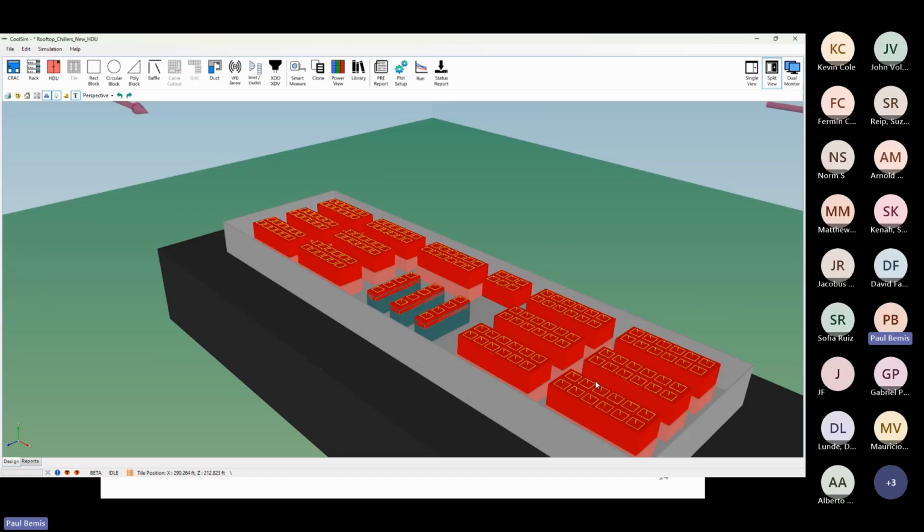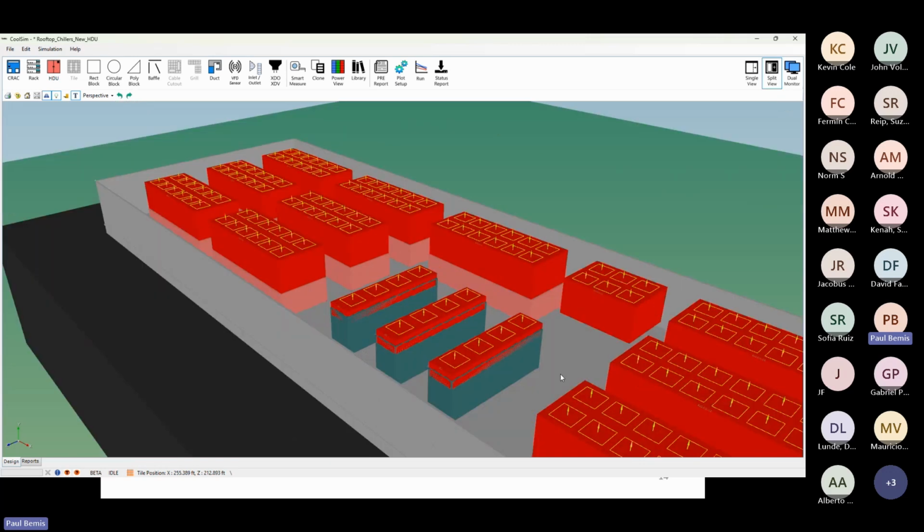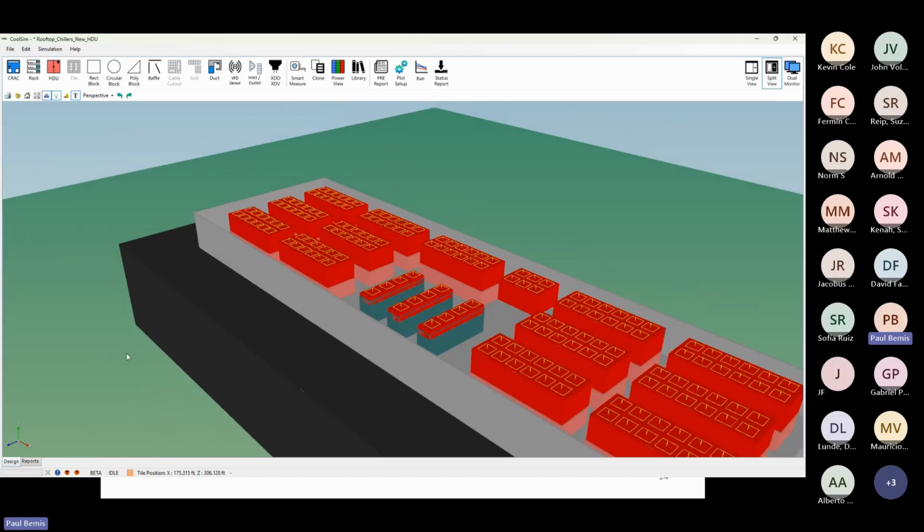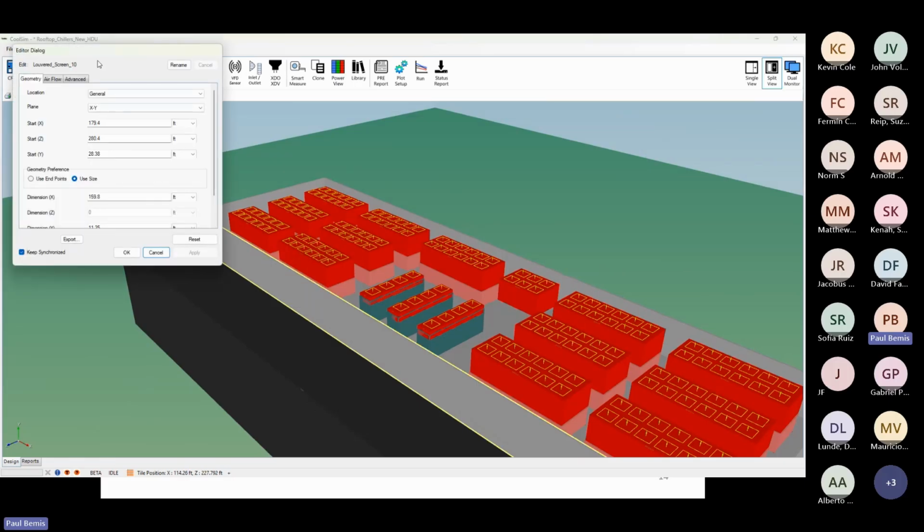You all are design engineers, I'm assuming. So you understand the symmetry here is typical because it allows you to do plumbing more effectively and piping more effectively, etc. This particular design has a screen around it. You see it right here. This screen is not unusual. This is a louvered screen. They do this for beautification as much as anything else. It causes issues for flow, typically, but it's there.